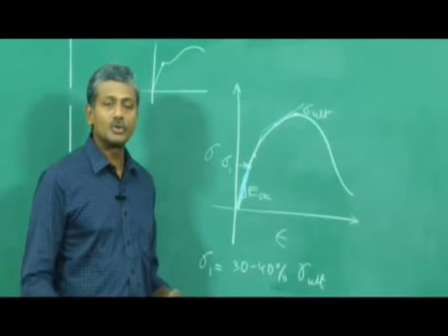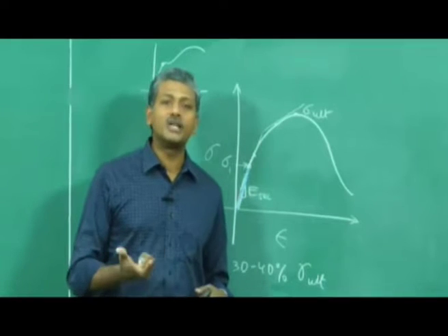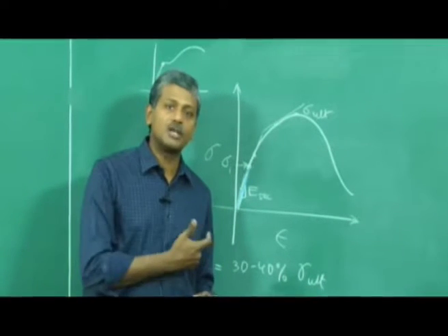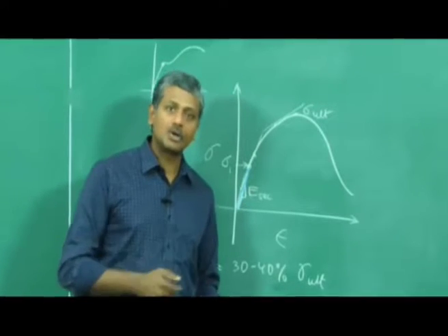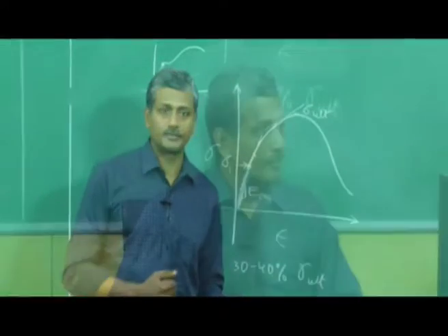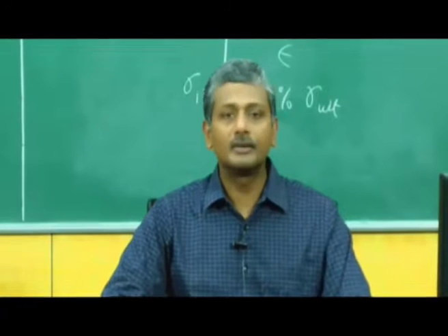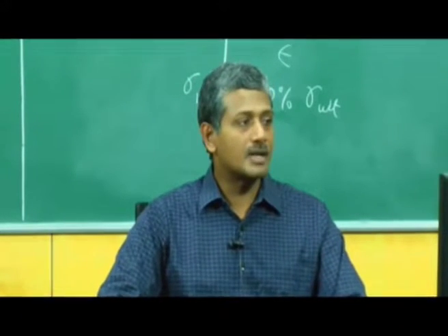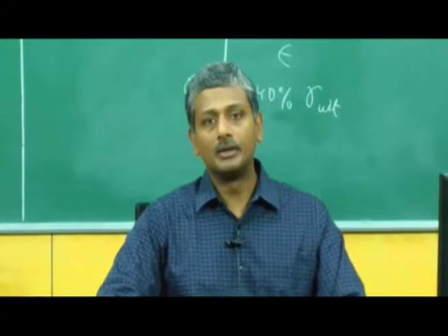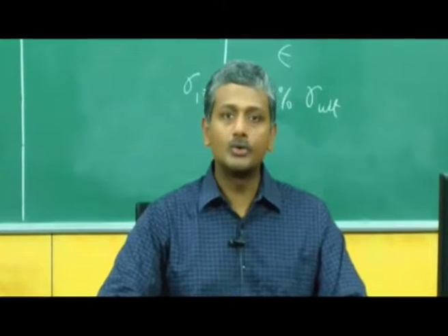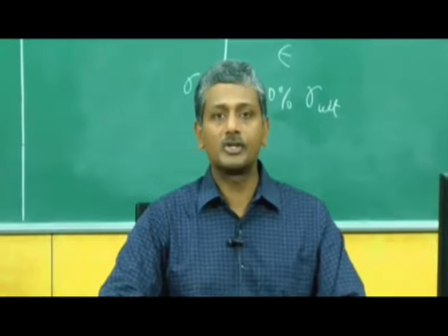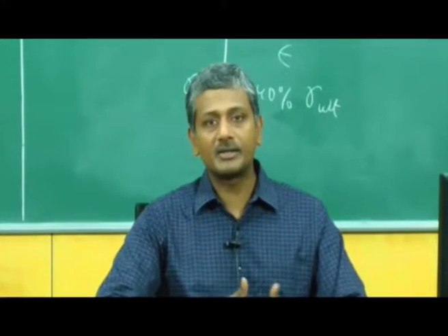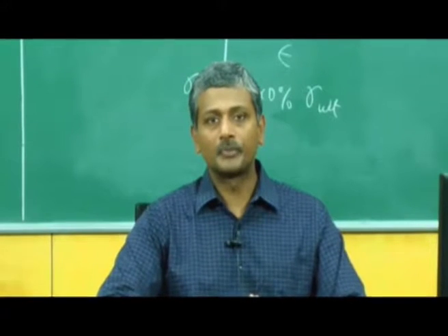I said before that because of the non-linearity, you can't truly define a single modulus of elasticity for the concrete. What is accepted in most codes as the modulus is the secant modulus. Again, the question is a continuation of the previous one: in design, which modulus will be taken? As I told you earlier, all codes agree primarily on determination of modulus by the secant modulus method, and this is the kind of modulus that will be considered for design purposes also.